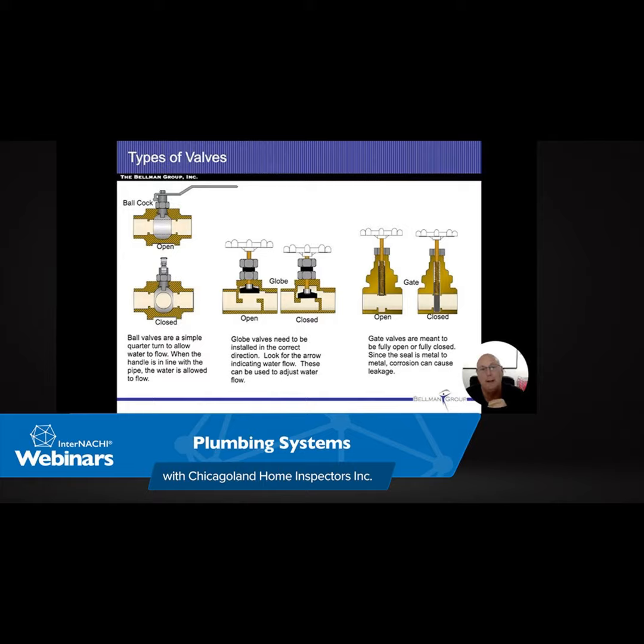But we don't want to own it either. We don't want to be paying to have it done right. So we're going to talk to our clients, and we're going to let them know the worst case scenario. You turn the water on again, run it slower, fill the trap back up again, and this way we could prevent those sewer gases from coming into the building. I just want them aware that it could happen.